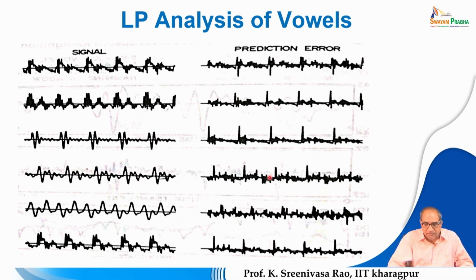There are other places where there will be noise at other parts of the signal also, but otherwise the common observation in the case of voiced segments is this: if you analyze the error signal, at periodic intervals the maximum error, the peak error, can be observed.